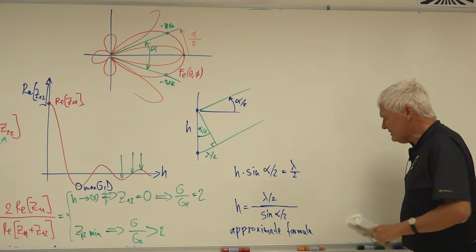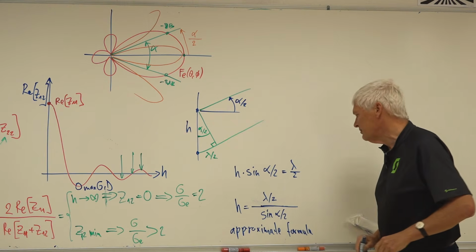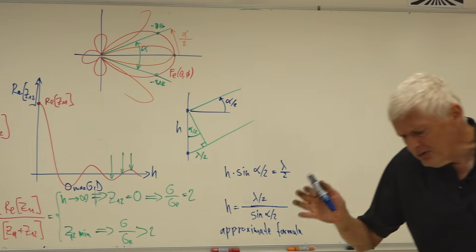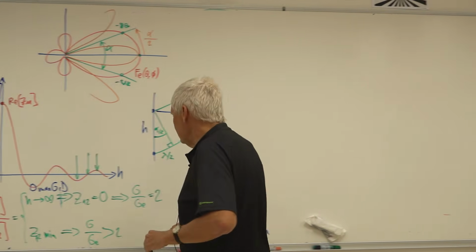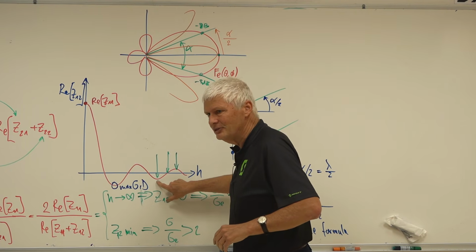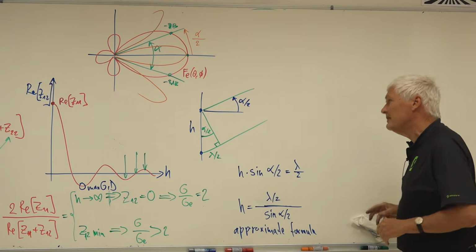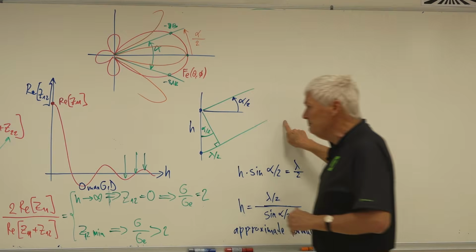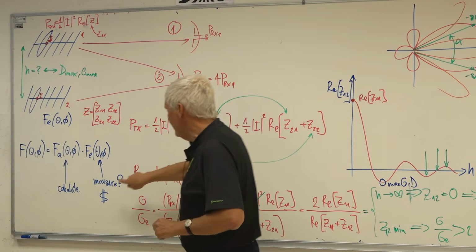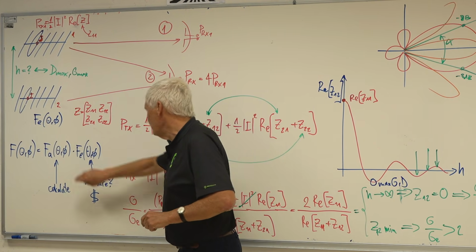So this is usually cited as truth in many antenna books, especially for radio amateurs, but it's actually the wrong formula. It's an approximate formula about that spacing, but you don't know whether you are going to hit here the hill or the valley. You don't know that in advance. So this is sold as a true formula, but it's just an approximate formula. But it's much cheaper than measuring the mutual impedance, and still much cheaper than measuring the radiation pattern. This is by far the most expensive.